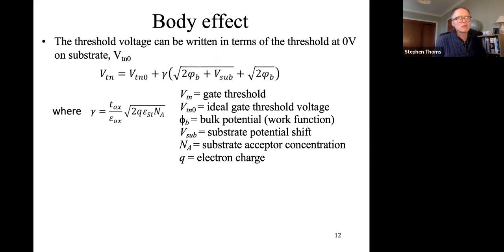Yeah, is a transistor in a pinch-off state then, if the substrate or body potential for the NMOS rises? Then it is pinched off. Obviously it depends on the relative potential between the gate and the underlying semiconductor.